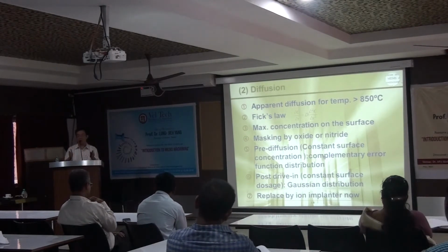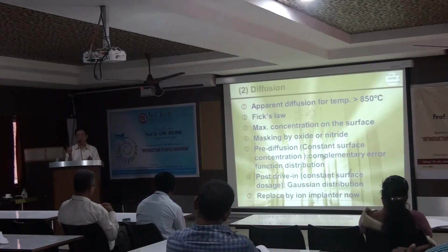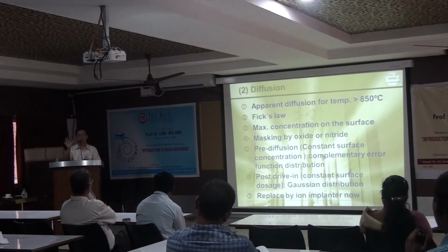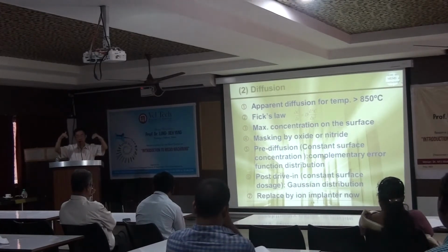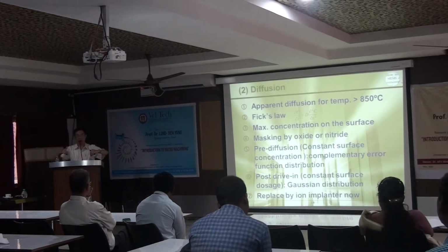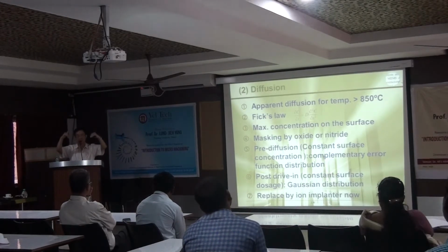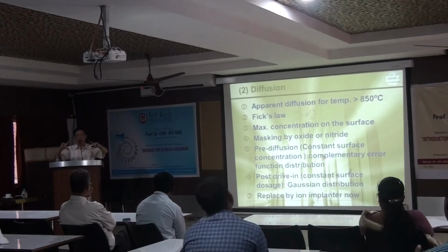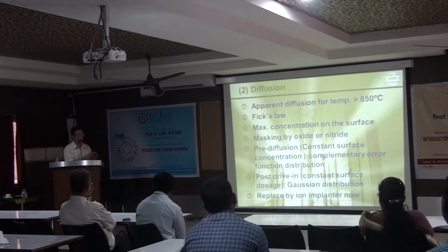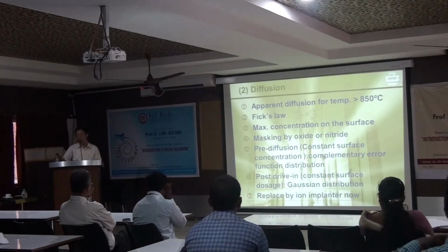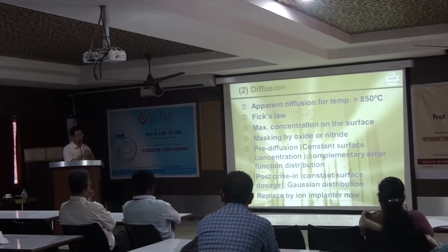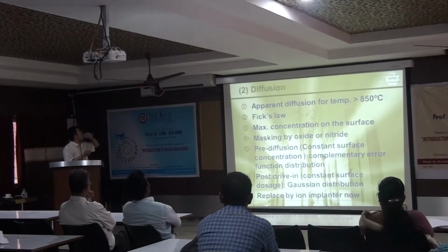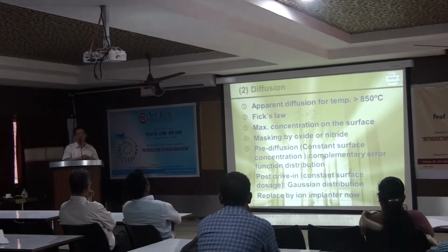Under such a situation, we stop releasing the dopant. We only keep the temperature over there. So the surface dopant will keep diffusing to the underneath area, will keep going down to a deeper area. So you call it the drive-in. This process is very similar to the thermal treatment of a metal.